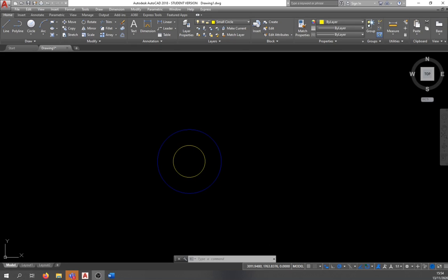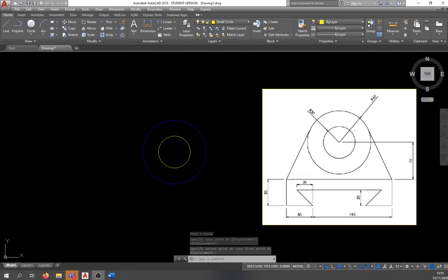The next thing we're going to do is the outline. Just for myself, flipping back between screens, I copied the image into AutoCAD. This is actually a straightforward thing to do. Basically, I went into Microsoft Word, clicked on the image, Control C, brought it into AutoCAD and pressed Control V to paste it in, and it showed up right here. So it's a handy way to do it if you need to.